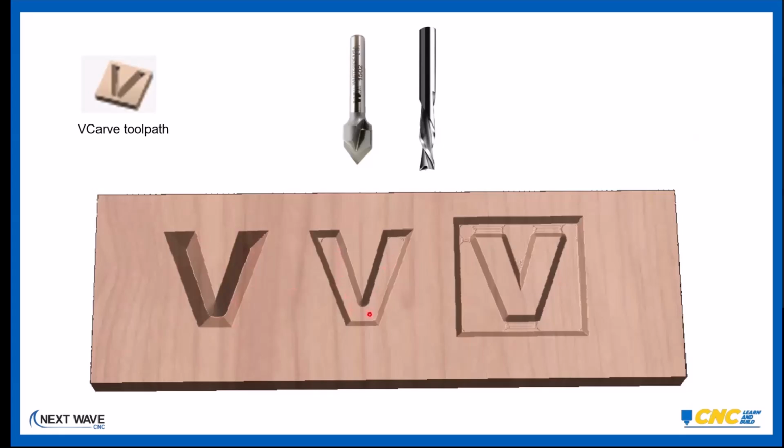This one has a flat depth, the one in the middle, using the same shape, the V, but either the tip of the router bit, the V bit, flattens this out, or you could use a straight bit if the shape is large enough to go in there and clear out the flat area also.